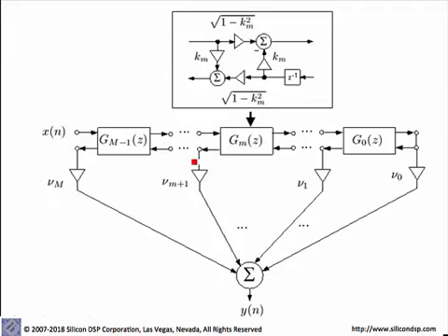The normalized lattice filter does not have any overflow and maximizes the use of the dynamic range given the word length for implementing that digital filter. The only place you may have overflow is when you accumulate the results of weighting of the normalized lattice sections as shown over here, which of course you can control using appropriate scaling schemes.